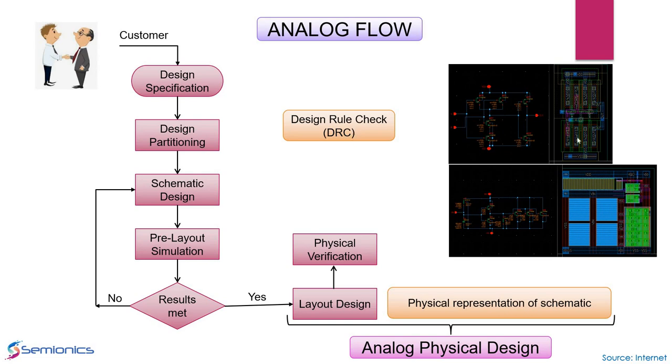So if he's designing a gate or a digital or analog design, he needs to follow a certain set of rules given by the Foundry and verify that the design is meeting the requirements from the Foundry. That is what is called design rule check in simple terms.